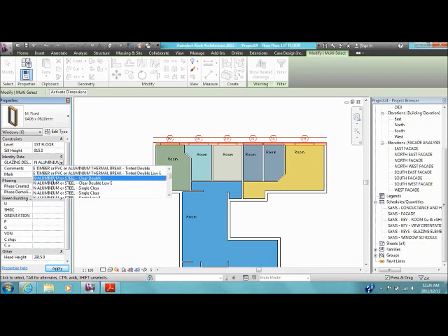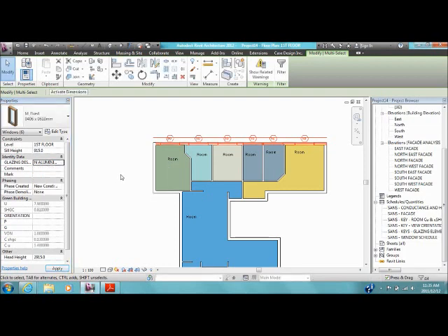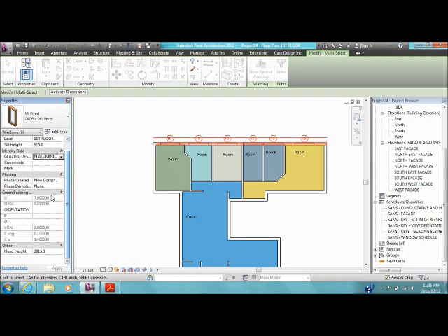I've broken these down into view orientation, so north, east, west, south, and so forth. And I'm going to say, listen, this is an aluminium or steel frame window in a northern elevation, and it uses single clear glass. As soon as I select that, all of the windows get the appropriate information filled into them. At this stage, because it's a uniform building, I can also say, listen, the P value, in other words my overhang, is 600 millimeters. So I can fill that out.